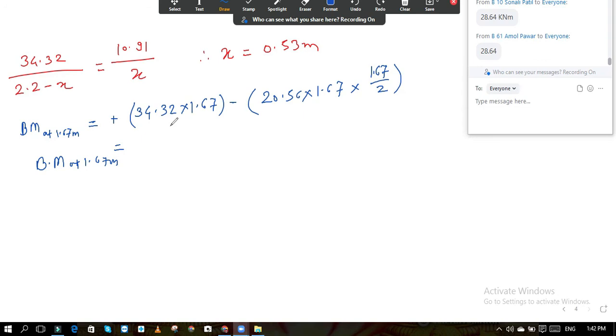Okay. So this is the bending moment for flight AB, maximum bending moment, and for flight BC it is 39.22. So again there is no need to take the check for depth, as we have already taken it for the higher bending moment than this.